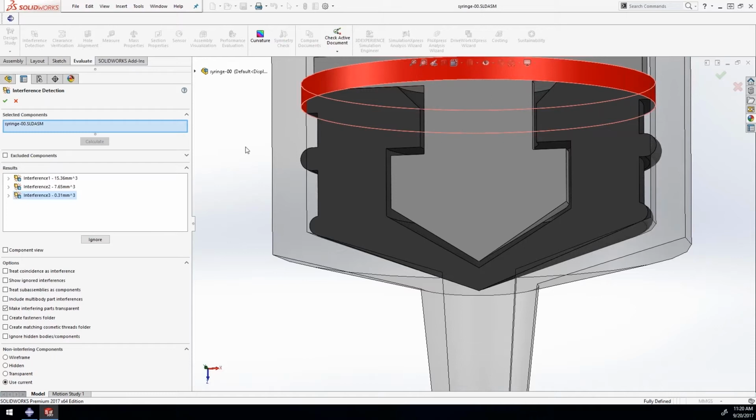In a nonlinear analysis, if we wanted to do this in Abaqus, it's possible that we could do it, but one of the limitations of a nonlinear analysis in Abaqus is that those shrink fits need to be resolved in the first step. And so if we had a problem where there's a large amount of interference that needs to be resolved, something where you're going into the plastic range of materials for a shrink fit, you're going to have a lot of trouble with those kind of analysis in SOLIDWORKS, just because that has to be resolved in the very first iteration. So we can't step through it, we can't reduce the time step, anything like that. And it can make problems like this difficult.